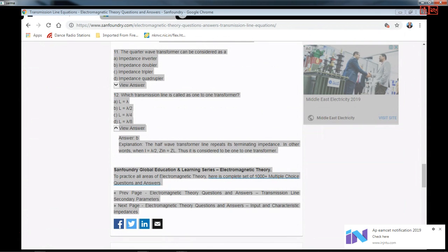In terms of cos and sine functions, what is happening is expressed in this. And please remember, we are taking that the small gamma is simply equal to j beta. That's why beta is directly appearing, though in the first two equations the gamma is appearing. Small gamma represents propagation constant, capital gamma represents reflection coefficient. That's how the notations go in this subject. Small gamma is our propagation constant, which is expressed in per meter, whereas capital gamma is our reflection coefficient, which is a dimensionless quantity, because it is a ratio of the voltages.